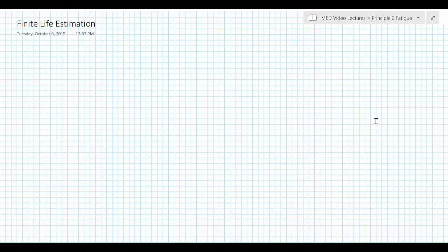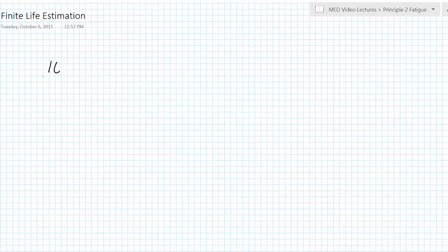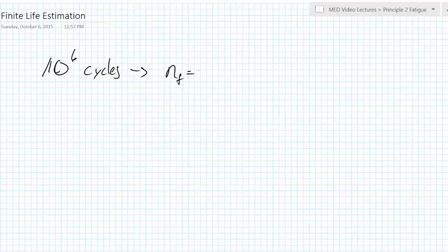Welcome back. In this video, we're going to talk about finite life estimation. Up till now we've been asking whether this thing is going to have infinite fatigue life, or is it going to last at least 10 to the 6 cycles? And if so, we say that the fatigue factor of safety is 1. If it can last more than that, it'll have some greater fatigue factor of safety. But we don't really have a way of estimating how many cycles it will last beyond 10 to the 6.